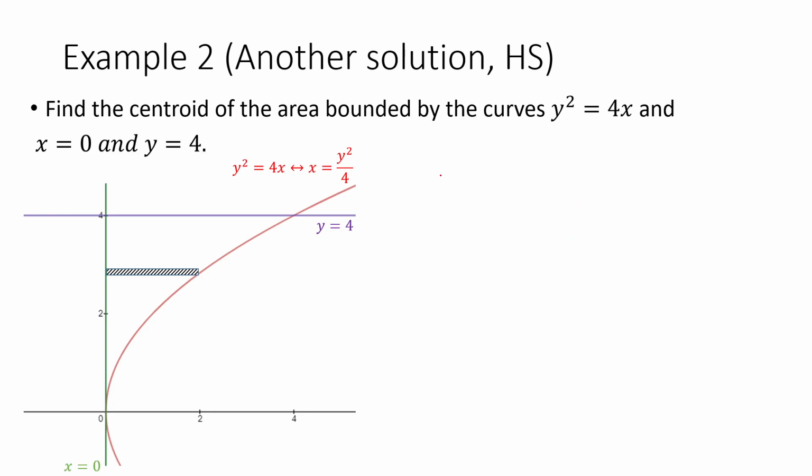Okay, so for the last portion we're going to solve for bar y. So y sub c times the differential area. And again, since we are utilizing the horizontal strip, this is from y1 to y2, y sub c, then x right minus x left, dy.